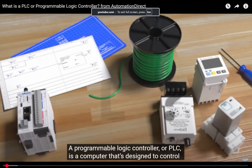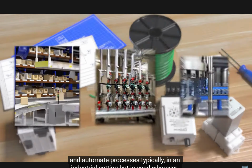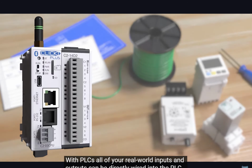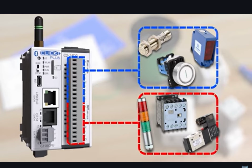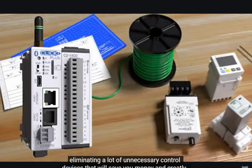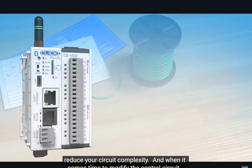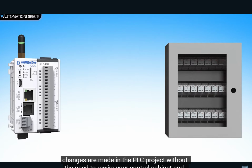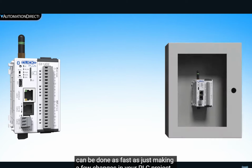A programmable logic controller, or PLC, is a computer that's designed to control and automate processes, typically in an industrial setting, but is used whenever you're looking to reduce human interaction and increase precision and efficiency. With PLCs, all your real-world inputs and outputs can be directly wired into the PLC, eliminating a lot of unnecessary control devices, which will save you money and greatly reduce your circuit complexity. And when it comes time to modify the control circuit, changes are made in the PLC project without the need to rewire your control cabinet, and can be done as fast as just making a few changes in your PLC project.